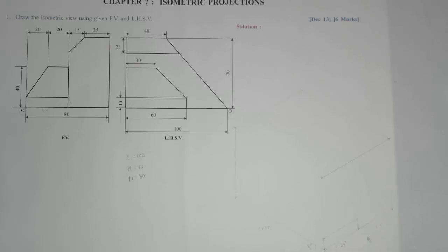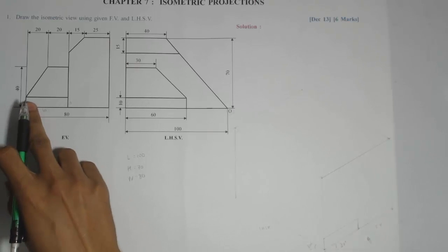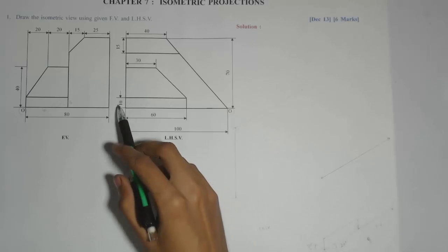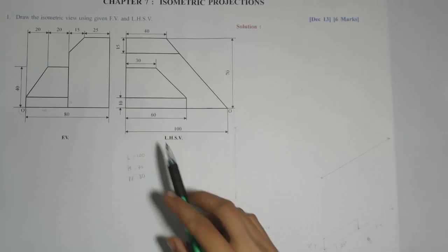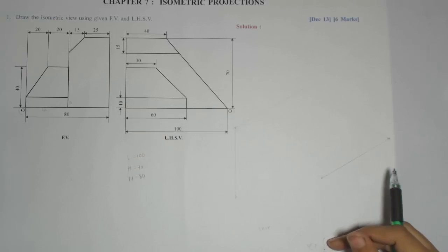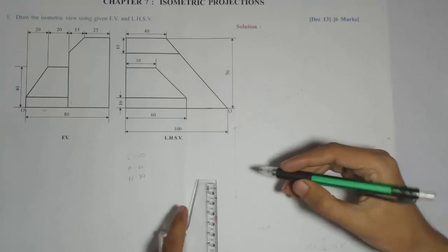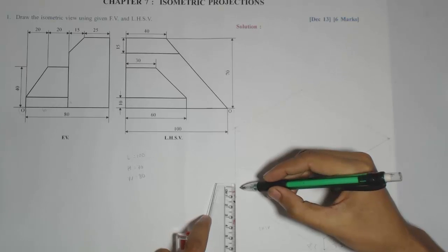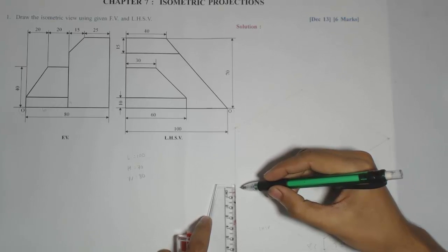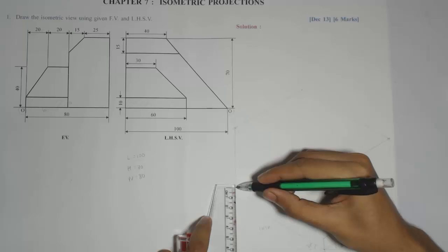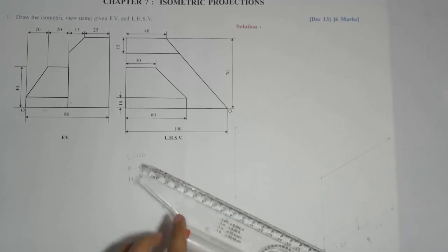So you have drawn this front view rectangle of height 10 mm. Then corresponding height 10 mm I'll draw in the left hand side view, but not starting with the origin, but exactly from the opposite boundary from the origin. So I'll mark that common height 10 on this boundary of the rectangle.